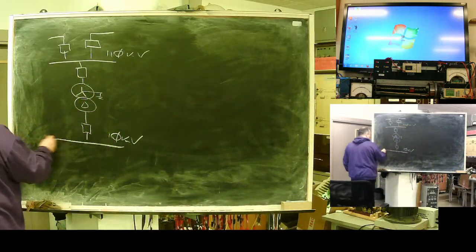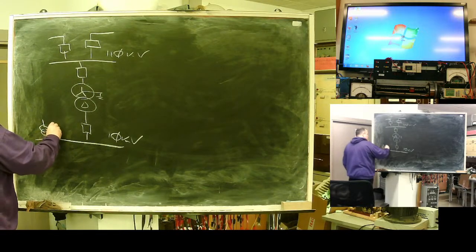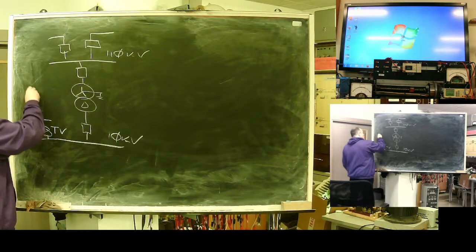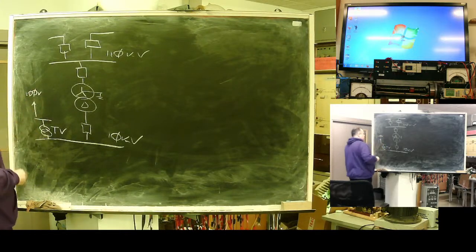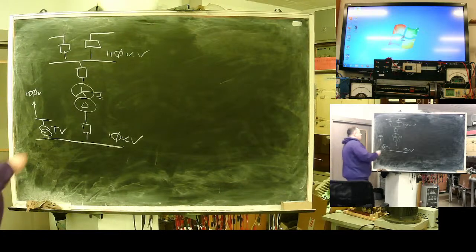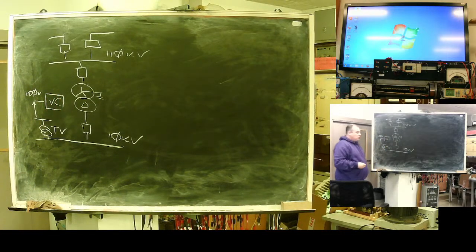From the middle voltage bus, via a special measurement transformer, 100 volts measured voltage is taken and taken to the voltage control device.